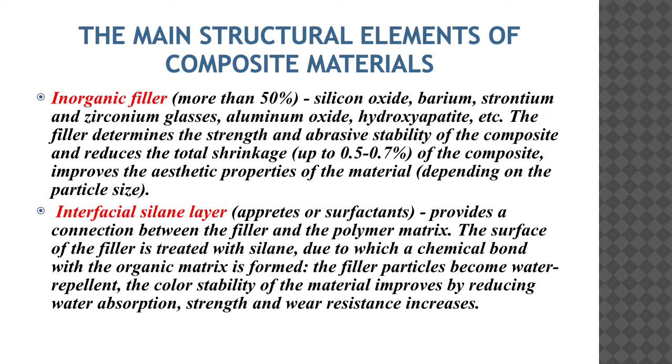Interfacial silane layer, which may be called coupling agents or surfactants, provides a connection between the filler and the polymer matrix. The surface of the filler is treated with silane, due to which a chemical bond with the organic matrix is formed. The filler particles become water repellent. The color stability of the material improves by reducing water absorption, and strength and wear resistance increase.